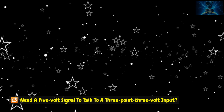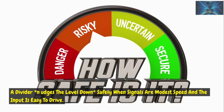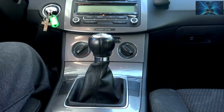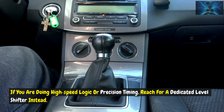Use case 5: gentle level shifting. Why it applies: need a 5-volt signal to talk to a 3.3-volt input? A divider nudges the level down safely when signals are modest speed and the input is easy to drive. If you are doing high-speed logic or precision timing, reach for a dedicated level shifter instead.